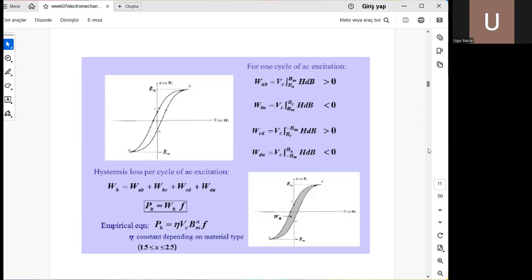So there's a kind of two-way path of circulating magnetic flux density in a material, which results in given magnetic field energy. Note that the magnetic energy is the area between the nonlinear curve and the vertical axis. If the two paths of magnetic flux density curves follow different paths, then the areas are different.